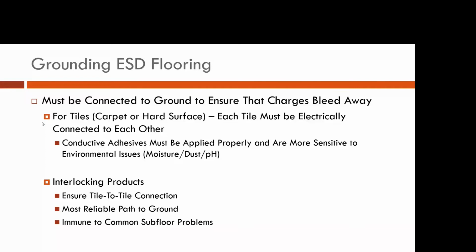In the carpets or glue down tiles or rolled sheet goods, the conductive plane is created with the adhesive that is put down on the floor. With the epoxies, there is an electrocoat that's usually put down underneath the top coat, and that is your conductive plane.